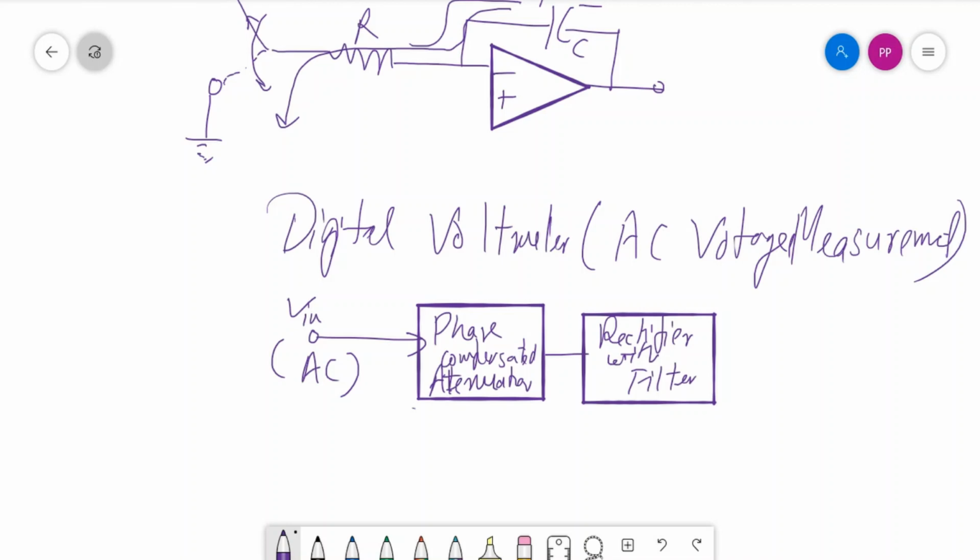In case you are taking the bridge rectifier with capacitor filter, the peak of the input voltage is kept with a mild ripple in the output. So we can use the ripple filter at the output, and the capacitor will produce almost the peak voltage of the AC supply input to the circuit.